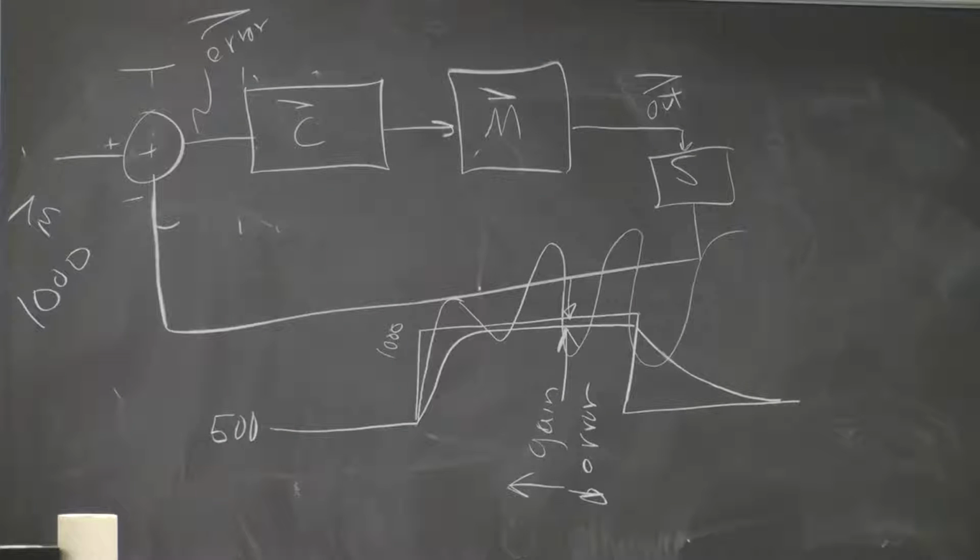Well, it's the phase shift that's messing us up here. The phase shift is too high at high frequencies. 180 degrees phase shift is enough that it destabilizes the system because it changes subtraction into an add. So let's get rid of some of the phase shift at high frequencies.